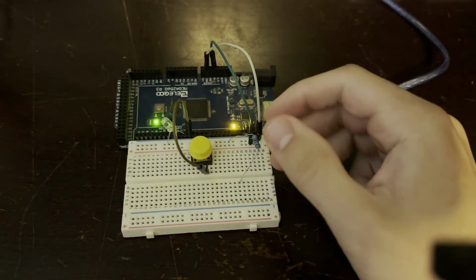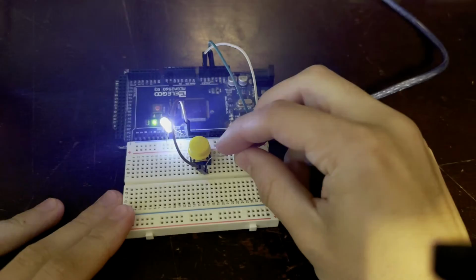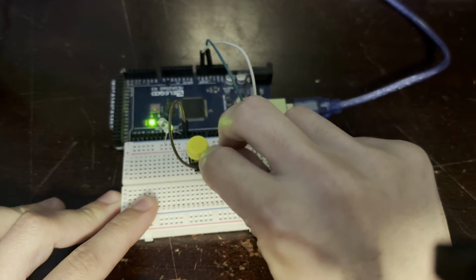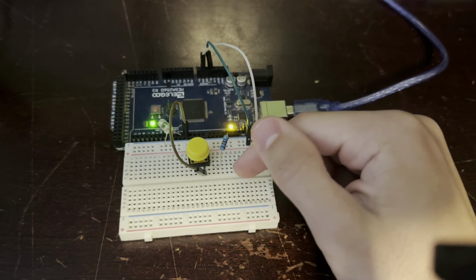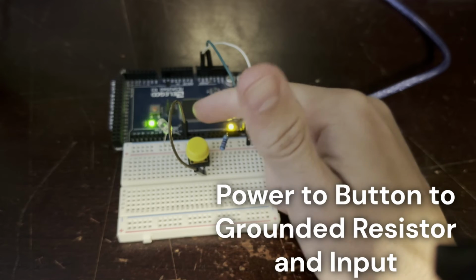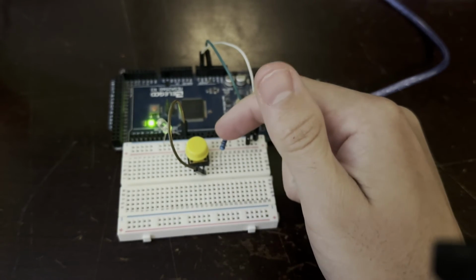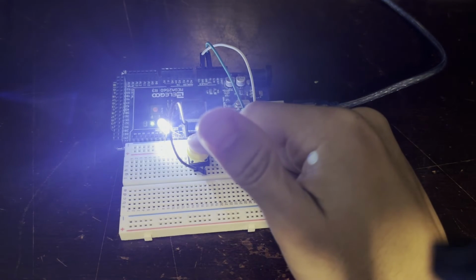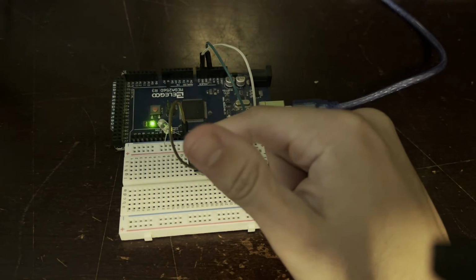I mean, the way we fix this isn't like in the simulation with the tri-state buffer that we're about to discuss, but all you gotta do is make the input defined, and we do that by wiring a resistor up with the button to ground. So now this wire is connected to ground through this resistor, so the Arduino knows that the light's supposed to be off. And then when we press it, we send a high voltage to the input, and the Arduino can detect that and know the light's supposed to be on.